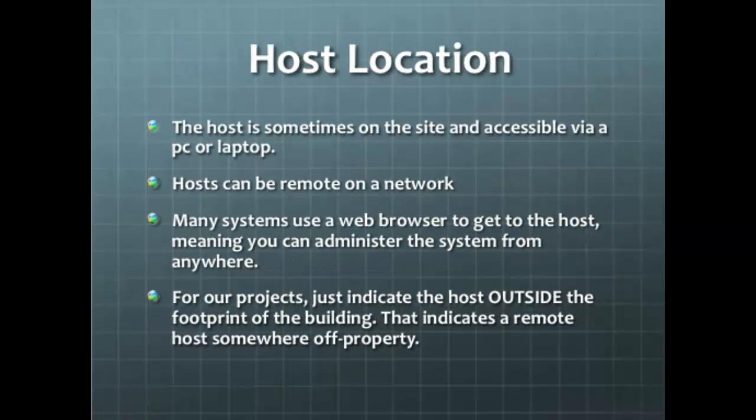So the final thing I want to talk about really quick is host location. The host computer is the thing you sit at, a computer, server, whatever it happens to be. You sit at this with a monitor, and it's where you program everything in. I want Brian to get in and out of this door. We can set time zones on these things. We'll go over that a little bit in the future, where I only want Brian to get in from 6 a.m. to 6 p.m., and then his badge shouldn't work here. I want him to get into doors 1 and 2, not 3, but 4. You can program all those things in the host. That's what filters down to the panel, as you know. Then the panel is the thing that talks back and forth to the readers to allow it to make that decision. The host doesn't necessarily need to be in your building.